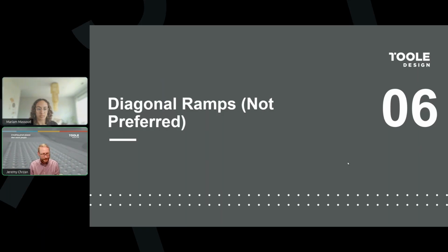PROWAG identifies these as being tied to the type of control that exists at that crossing. And so a stop or signalized intersection has different slope criteria. And the Access Board has acknowledged that this is going to be easy with new construction projects, but can be a challenge with alteration projects. And so you might be able to alter slope slightly with variable milling and minor adjustments, but you might not always be able to fully meet the criteria outlined in PROWAG.